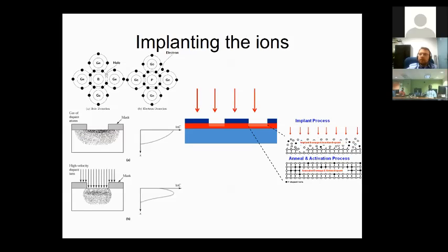Okay, so the ion implantation. So we talked about a different way of introducing ions. These would be the dopants. The first immediate way was the diffusion, if you remember. We could diffuse them into the substrate, and we could dope the silicon that way. But look at the example. It's not really well controllable. Diffusion is not so controllable, so it will also go underneath the mask too.